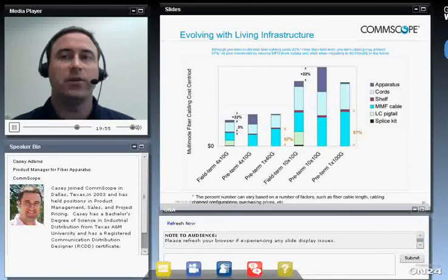by 10 gig versus the pre-term at 4 by 10 gig. You can see in the aqua shows the higher cost rate, with preterm cabling producing an overall cost that is 22% higher than field term. However, the migration path is limited to 1 by 40 gig for field term, and the investment to bring the data center up to a higher speed would require a secondary dollar spend equal to 57% of your original cost